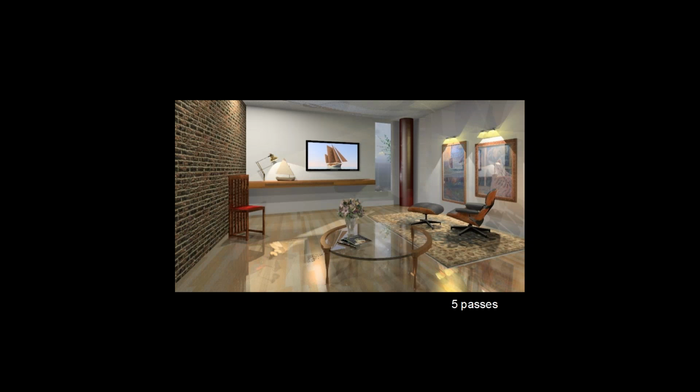Now you'll notice the floor in particular, that after just 5 passes, I'm getting kind of a mirror-like reflection. And so if you're impatient or you're not sure of what's going on, you may be inclined to make some adjustments. But actually, I want to tell you, don't do that. This rendering just needs more passes to achieve that satin finish on the floor that I'm after and to refine all of the lighting going on in this model.